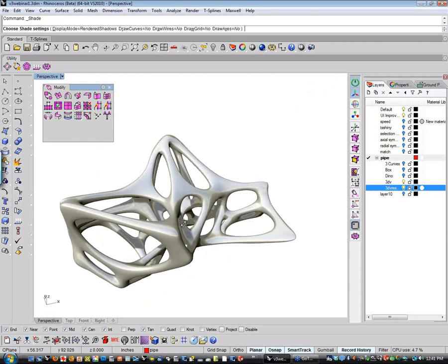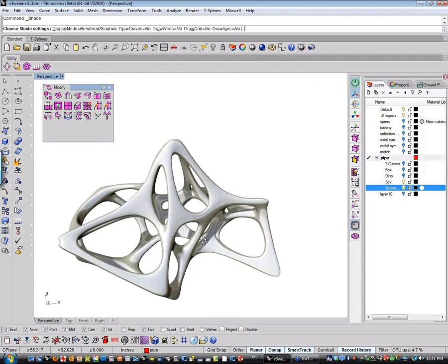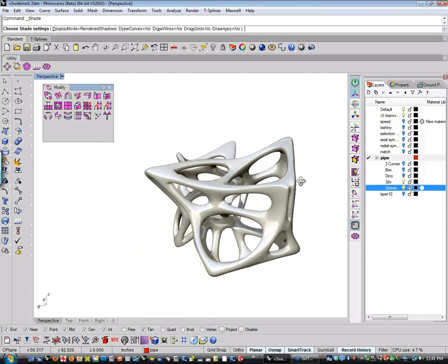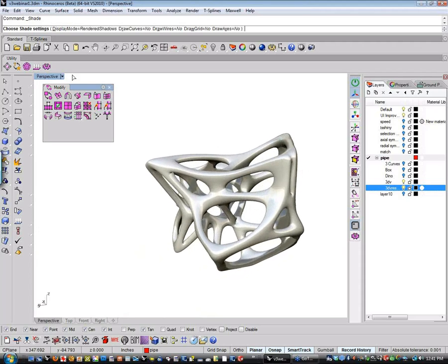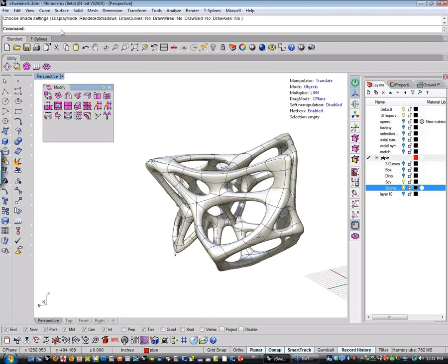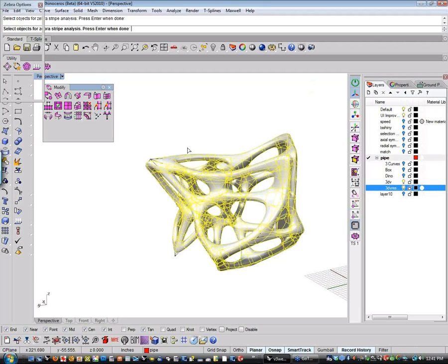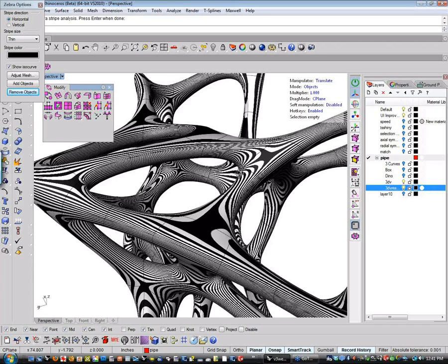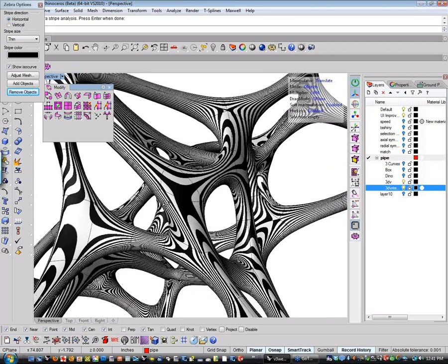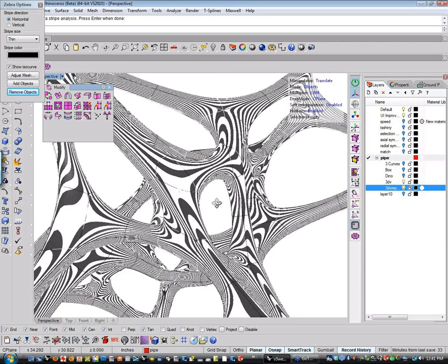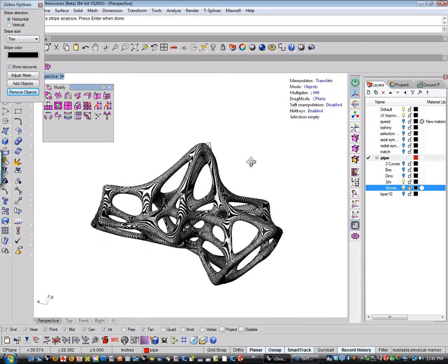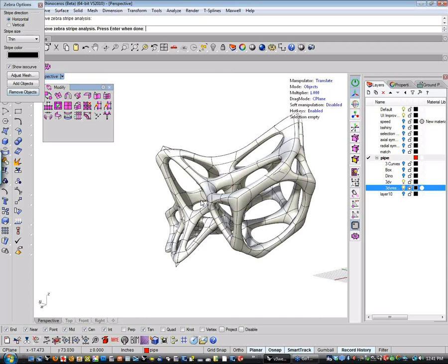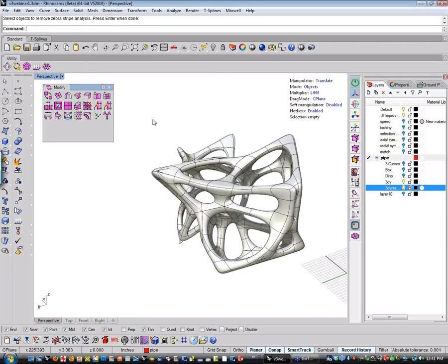And if you look, you'll notice that this is like a NURBS modeling nightmare right here. Y branches going into Y branches, going into Y branches, going into Y branches. And the coolest thing about this one is if we throw a zebra on this. Now, granted, we're working in fastest mode here, so the star points are going to be a little discontinuous. But you'll notice that you're getting curvature continuous connections all through this thing, which is pretty freaking awesome as far as I'm concerned.